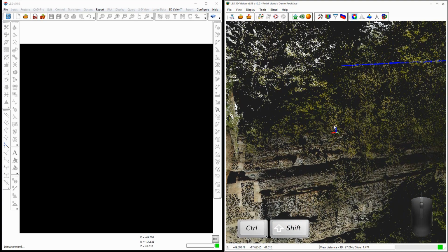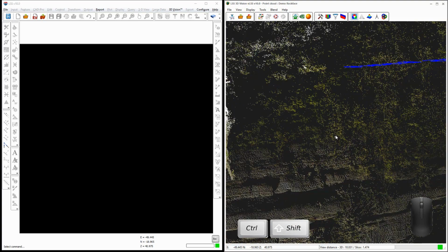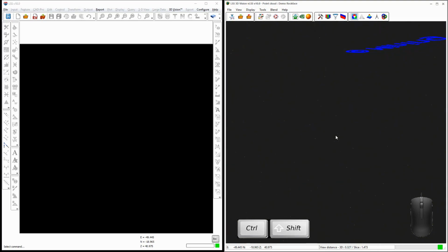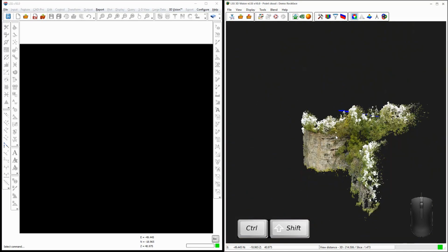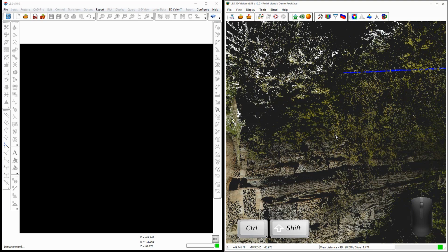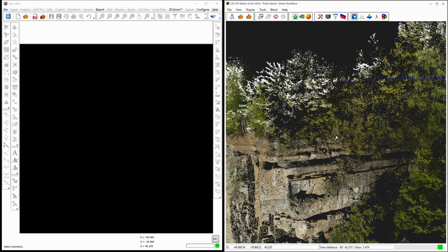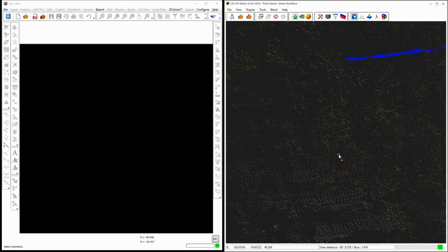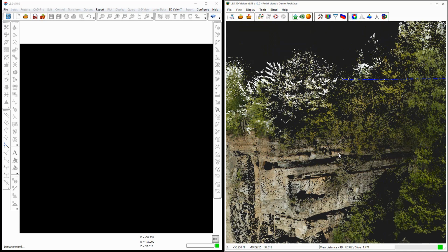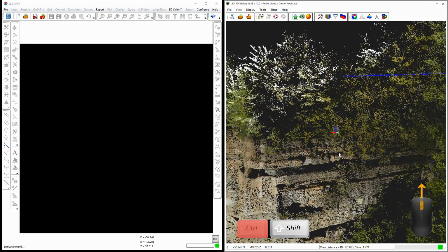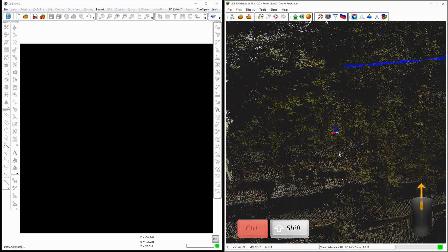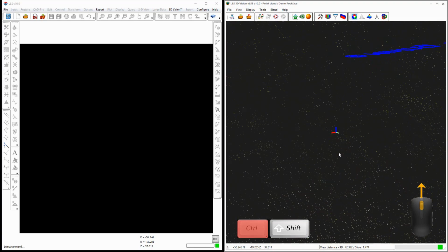so it's a matter of creating a focus point, and then you can zoom to it, but you won't be able to zoom through that focus point. It's like a length of elastic that you can go out as far as you like, but you can only get to the point where the elastic is attached. To do that and move through, you can hold the Control key down and now scroll with the mouse wheel, and that will go down the line, along the line of the elastic, through the anchor point for the elastic.